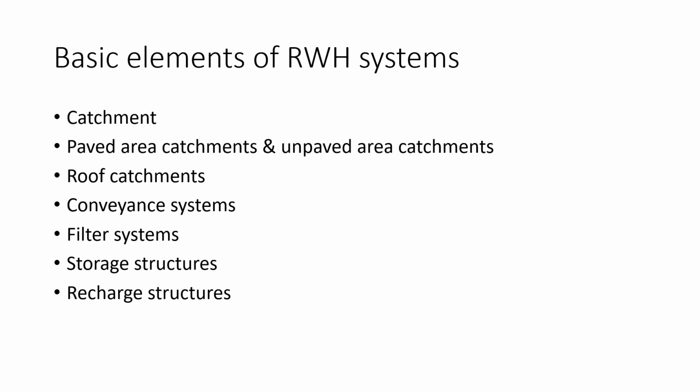Now this rainwater may be charged into the aquifers through recharge pits, recharge wells, recharge trenches, and dry dug wells or bore wells. As in the case of storage, there must be a system to filter out sediments and other debris before the water enters the recharge structure.